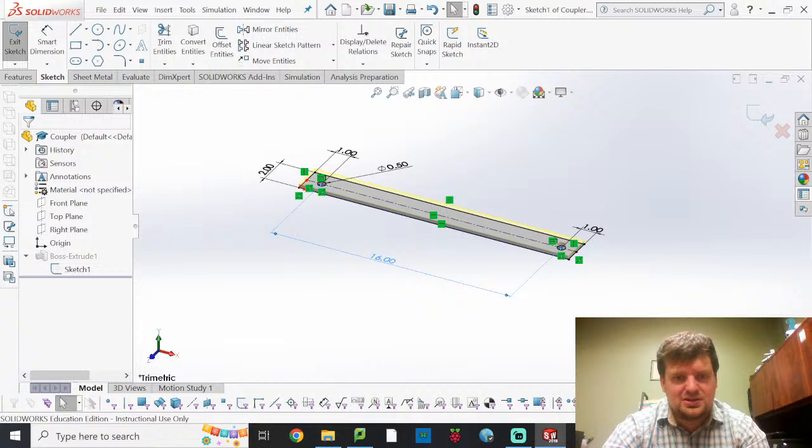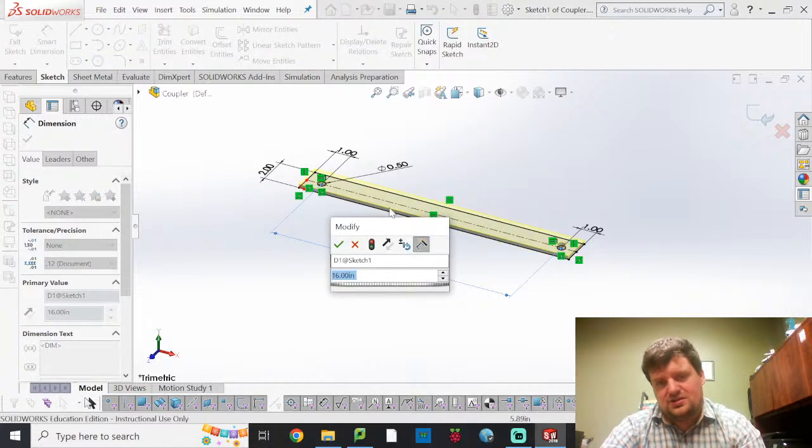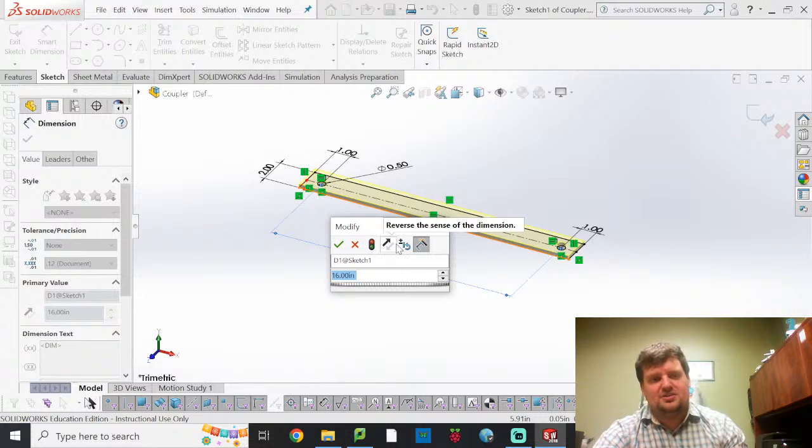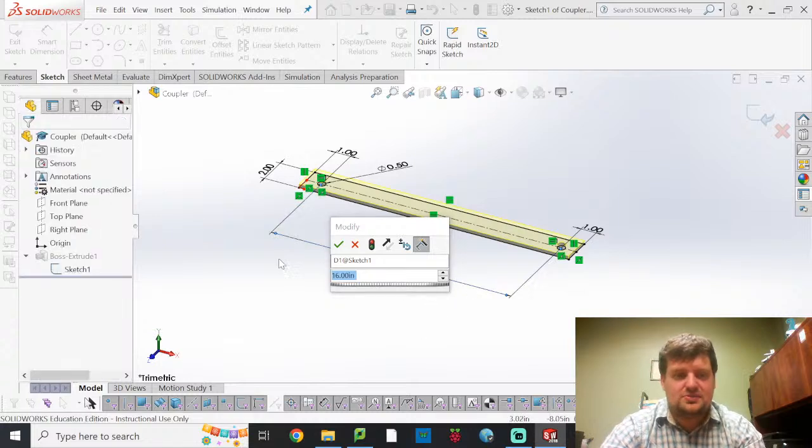here for my rocker, what you want to make sure is that your P plus Q linkage is greater than your S plus L. So here my S and L is going to equal 26. So this linkage has to be 10 inches or more. I'm going to make my rocker also be 16 inches. So I'm not going to change anything.